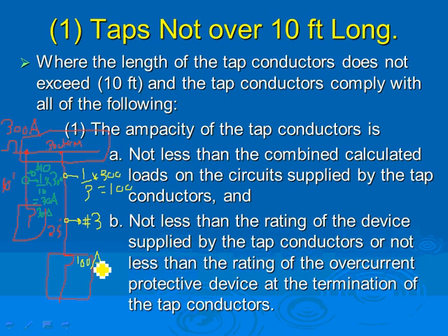Yeah, the max. Any comments, guys, about the 10-foot tap rule and the 25-foot tap rule? A lot of people take advantage of it, guys. You take a feeder, a 400 amp feeder, put it along the wall in your manufacturing floor, in a gutter, and you tap 10 foot with the fused disconnect and feed machine 1, machine 2, machine 3, machine 4. It saves you an MCC, a motor control center, a panel. So there's a lot of advantage to it.